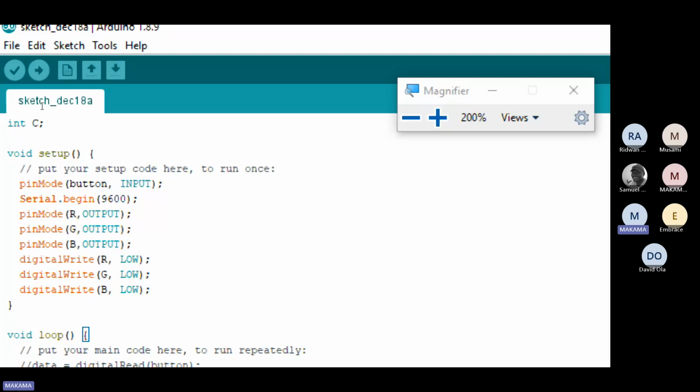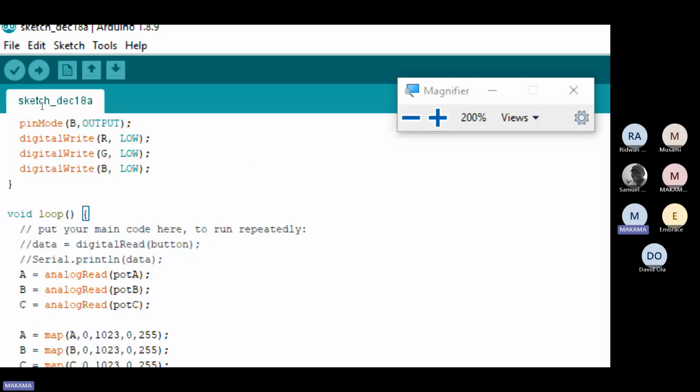The main difference between analog write and digital write is that in analog write you can output a range of values, like from 0 volt to 5 volt, like 2.5 volt, 3.5 volt, 4.5 volt. They are all in a range, right? But in digital you can only output either 0 or 5, 0 or 1, low or high. So that is the advantage of analog output.